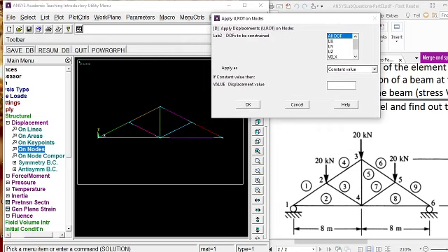But even for a roller support where we are arresting only in the y direction, we cannot straight away give that only uy should be arrested. Then it will take it as the velocity will also be existing in all the directions. So it will be a problem to us. So we have to arrest all the velocities in x, y and z. And even in the z direction also we are not allowing. Z direction is the direction in front of you, means front and back. We don't allow it. So we cannot just give the question as it is given to you. We cannot just simply give it to ANSYS. We have to give ANSYS the details.